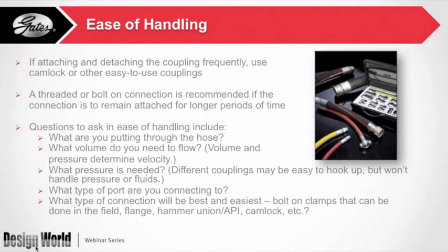What's the pressure needed? Always make sure that the pressure is not exceeding the pressure rating listed on the hose. And then, of course, make sure that the fittings and the hose are both made to meet the same pressure ratings. What type of port am I going to connect to? What type of connection is going to be the easiest? Is it going to be a bolt-on, or can it be hammer unions, API, camlock, and that sort of thing?